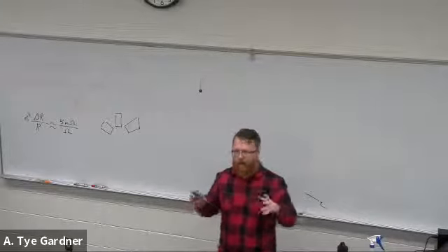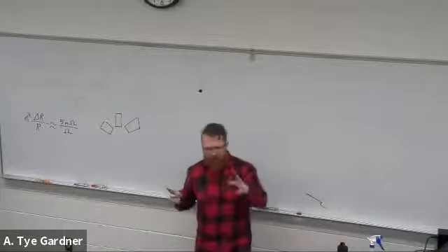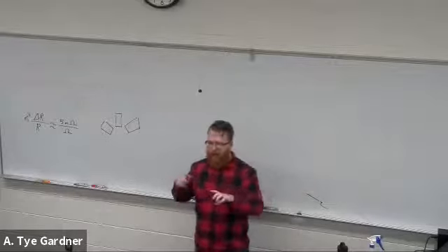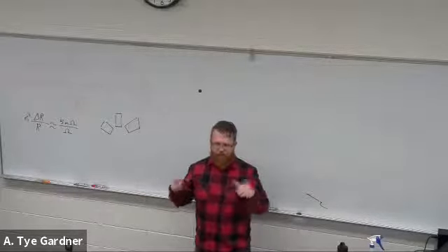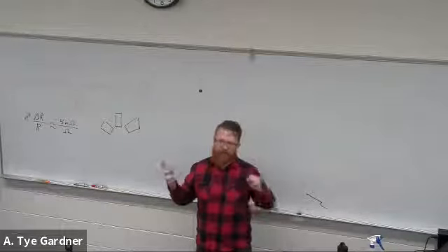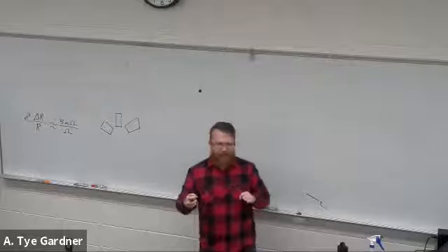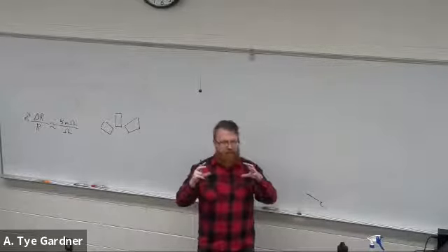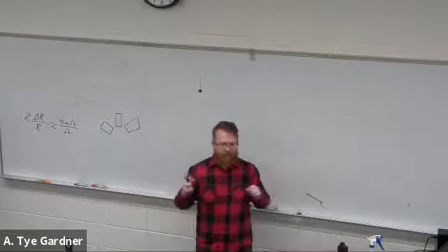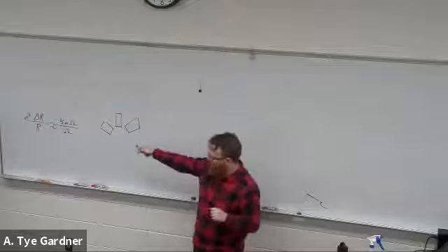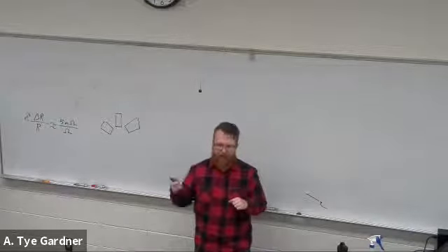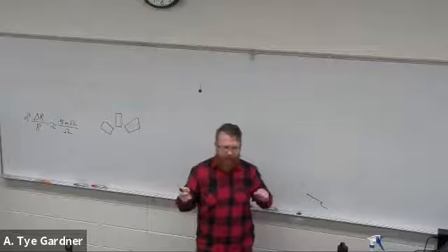Yeah, and I just remembered one of the cool ones: they'll put these sensors on flywheels for high torque systems to make sure that they're not about to explode and kill whoever's working with that engine, right? That's really common because the metal starts to deform long before an explosion. And so if you can measure super tiny changes in the delta R, you can shut the system down before catastrophic failure.